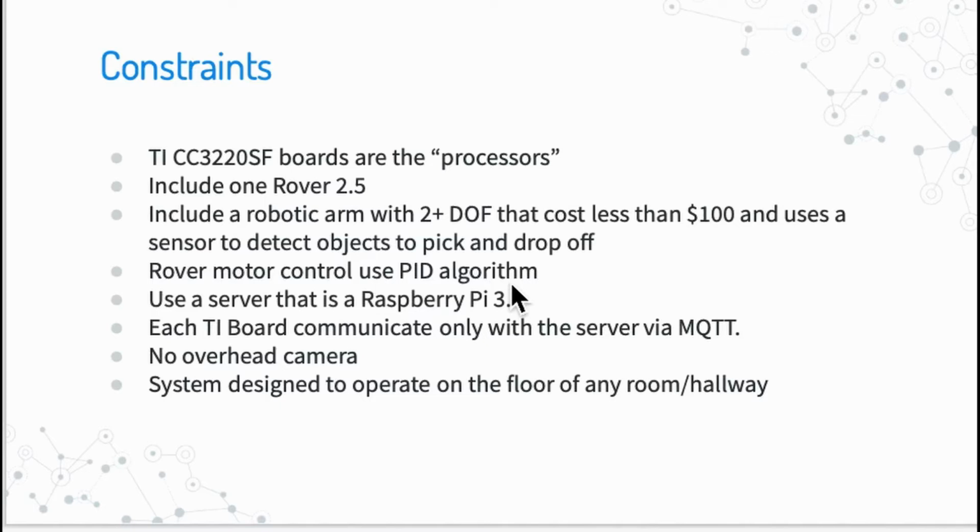pick and drop off. Moreover, for the rover's capabilities, we were required to use a PID algorithm for rover motor control. We were able to successfully use the PID algorithm to control the speed of each motor individually by reading the encoder values associated with each motor individually.